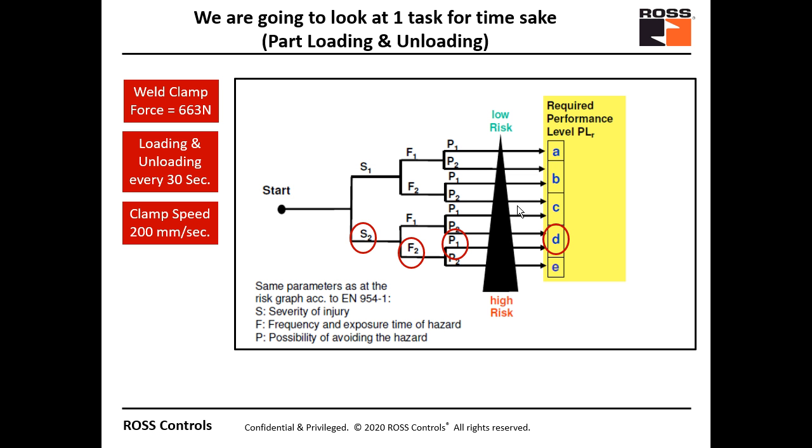And so if we apply this and start looking at this in accordance with the basic ISO 13849 method, we said in session 1, S1 is a slight injury. That is something that could be treated with in-house first aid. S2 is anything more than that in-house first aid. If someone has to go out to get stitches, go to the doctor, the hospital, or even to the morgue, it's a serious injury. There are other risk assessment methods that have 3 or 4 different severity levels, but this ISO method, as I said, is very basic, and it only has 2 levels.